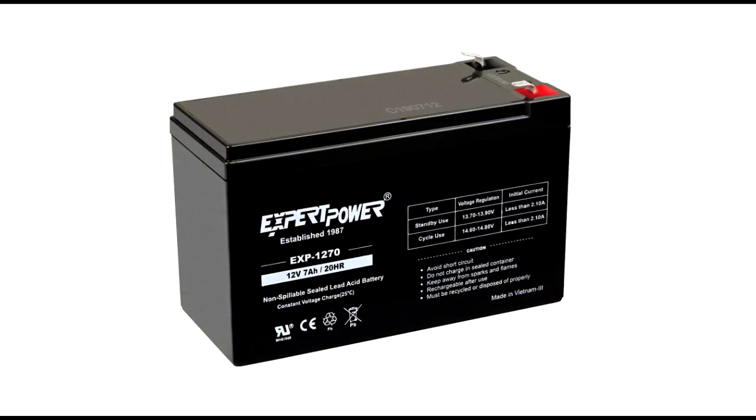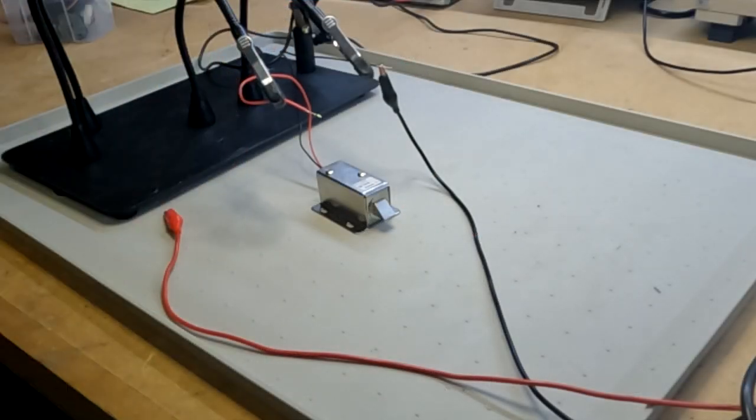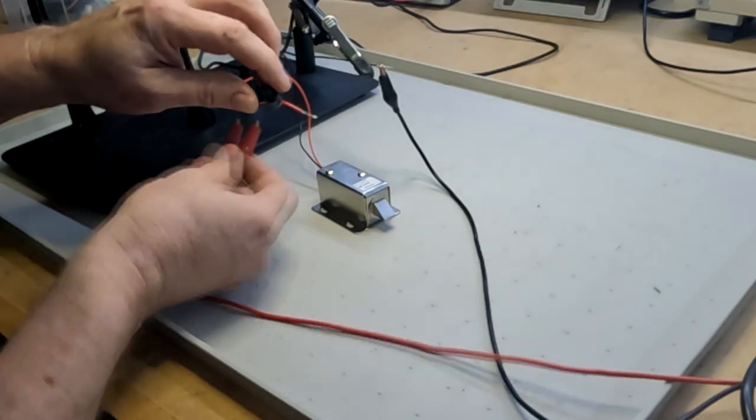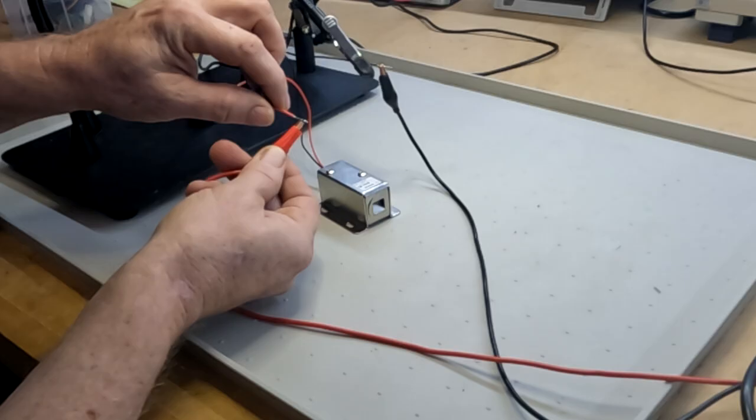The power supply in this project will be a 12-volt sealed lead-acid battery. This is the type often used in emergency lighting or alarm systems. They are very common and relatively inexpensive. The latch solenoid being used in this payphone is actually rated at 6 volts, but it will be brute forced to work on the full 12 volts. It will only be activated for a brief moment, which is not enough time to damage the solenoid coil. This will provide a strong punch to positively be sure that the door will open.